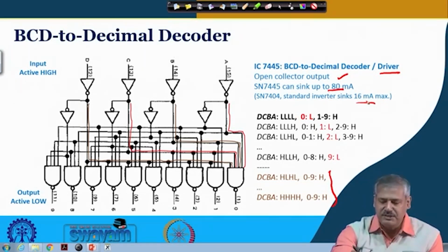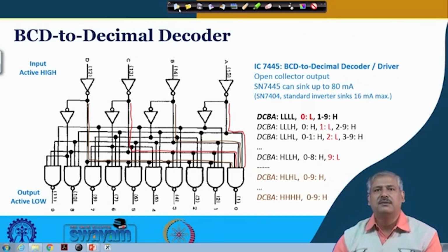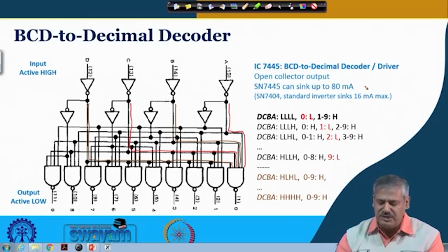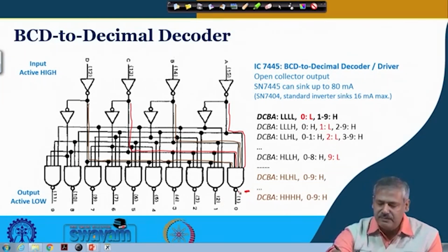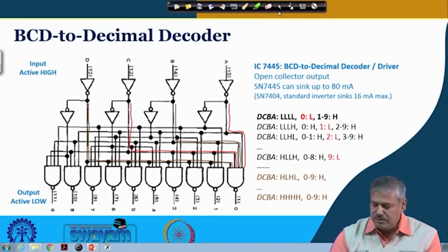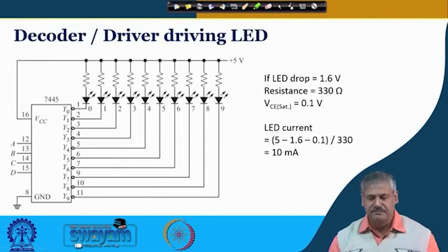Okay. So, this is useful, as I said, for displays and other things where the binary coded decimal and the corresponding display are connected in tandem. So, this is the meaning of decoder driver. The output stage of it will be open collector.